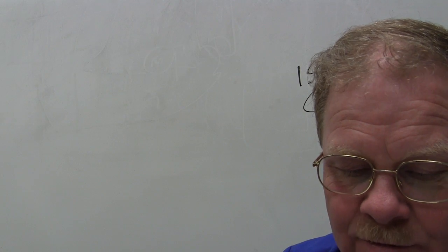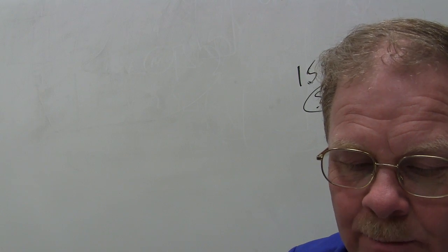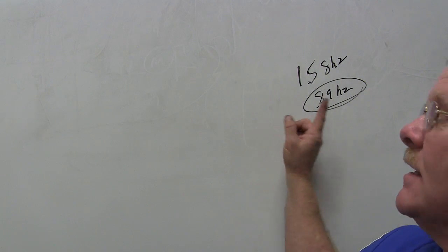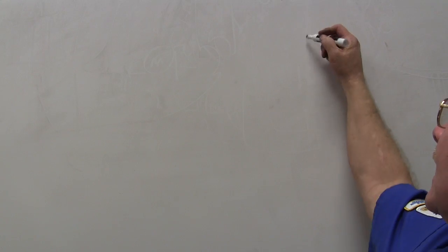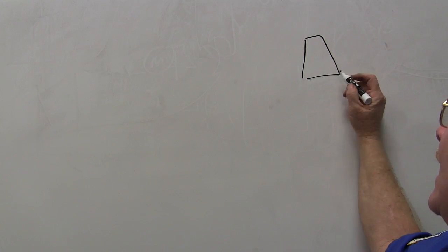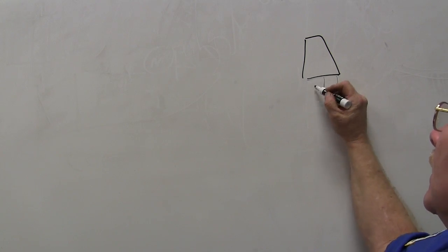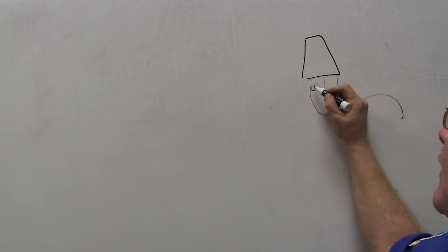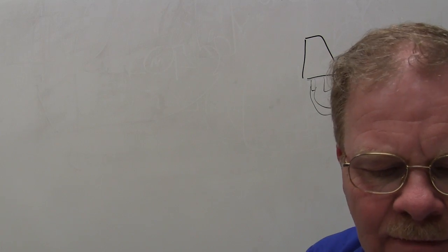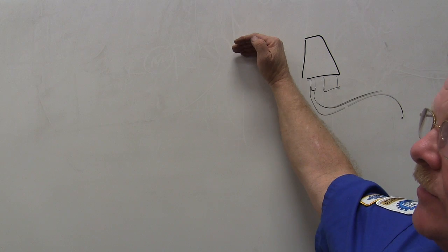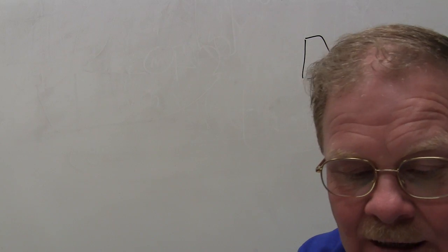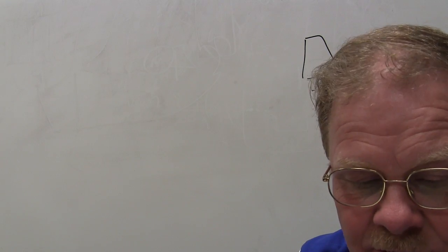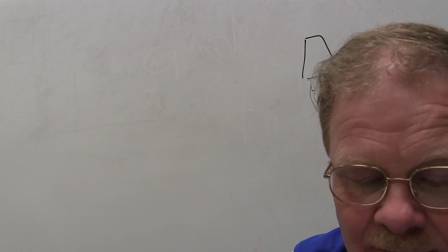Frequency output of a digital MAP sensor reading is 114 hertz. What's the approximate engine vacuum? Now this sensor I was talking about has a wire connector and a vacuum hose on it that goes over to the manifold, and it usually is mounted sideways. When you crank it up, it drops from about 158 hertz down to usually about 110 is what I've seen. It can be accurate at one end of that scale but not the other, so it's pretty dicey.